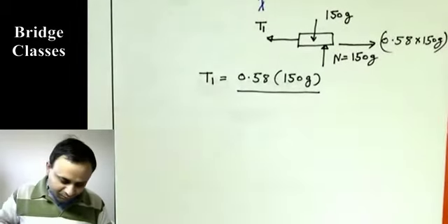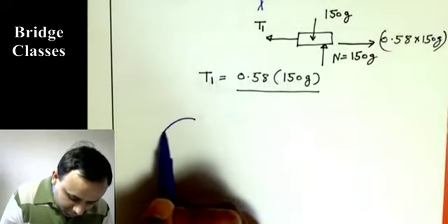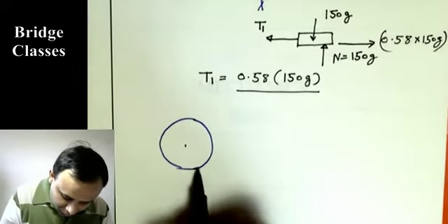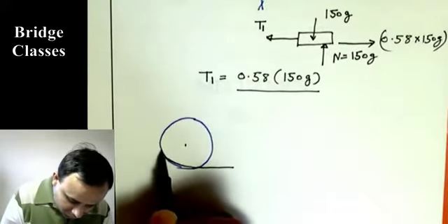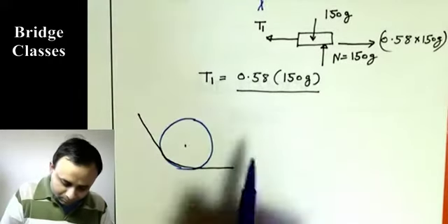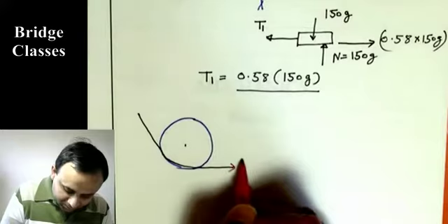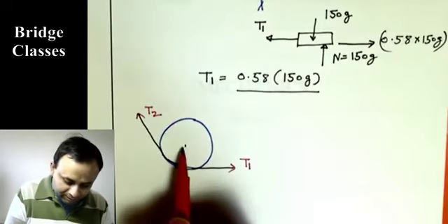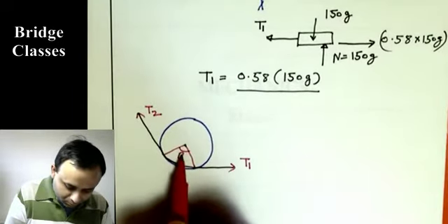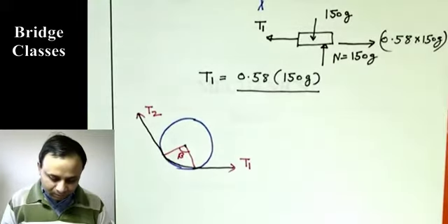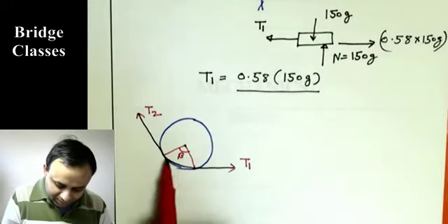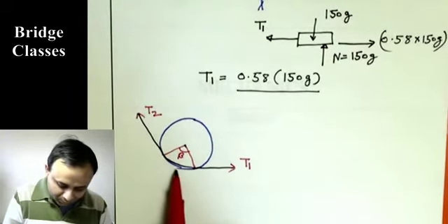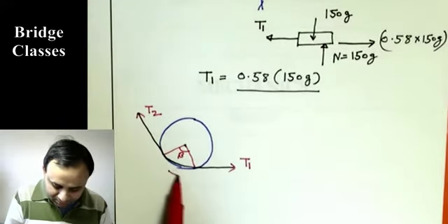Now, if we take a free body diagram for the belt around that pulley, the belt goes like this. It has force T1 here, which we already got, and this is T2, and this angle was beta. Because of friction here, the relative motion of the belt is in this direction, so friction acts in this direction.